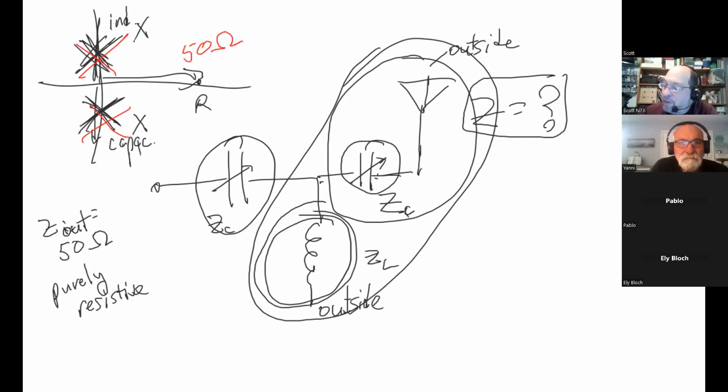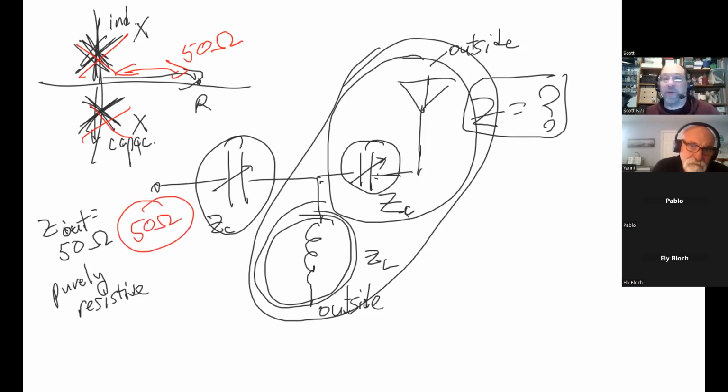We can also make this arrow go in and out by using that. By doing that, we can make our transmitter happy, which is really the goal of being able to put power out of a transmitter. If we have an impedance match of 50 ohms, pure resistive, then we have a happy transmitter. We have a good match in our system. And we will be covering that tomorrow.